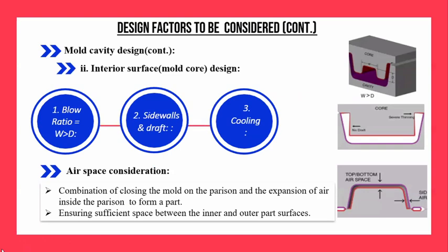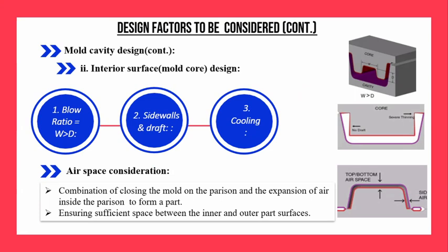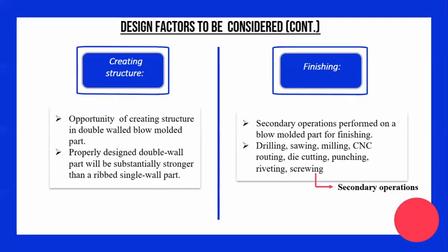In case of interior surface or mold core design, similar factors have to be considered as for the exterior. To ensure adequate blowing of air into each space of the part, sufficient space must be left between the inner and outer wall.